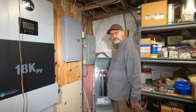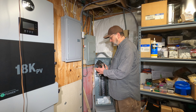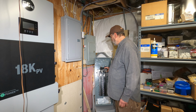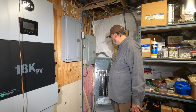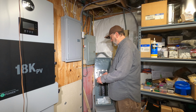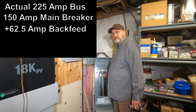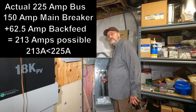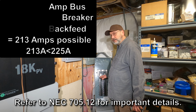If you are overloading the bus bar, you can decrease or derate the main breaker. So I'm actually planning to install this 150 amp main breaker, even though this bus bar is a 225 amp rated bus bar. Because if you add the 150 plus the 62, it comes in way below. And that leaves me more room to add potentially more solar in the future. Like if I put a solar system out in the barn, I can feed it into here also.